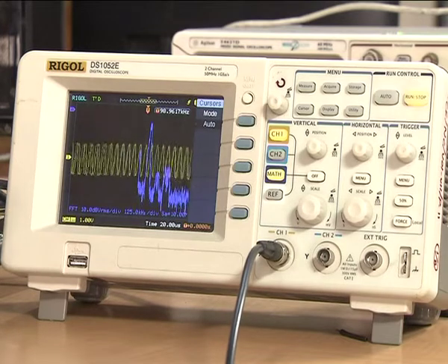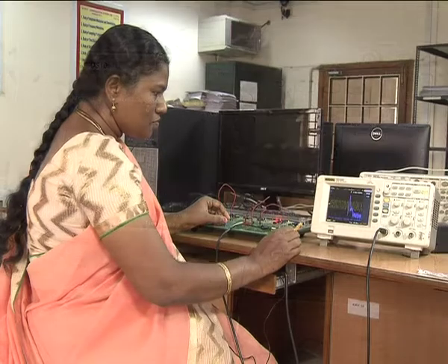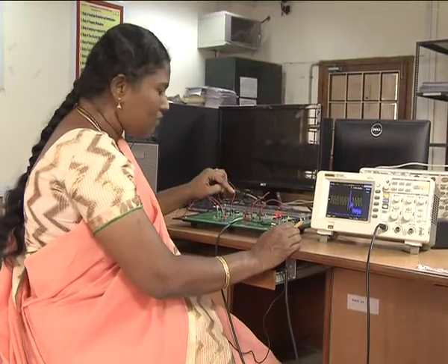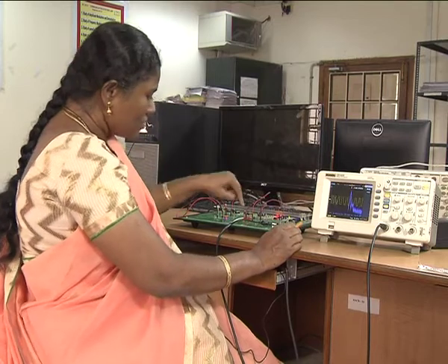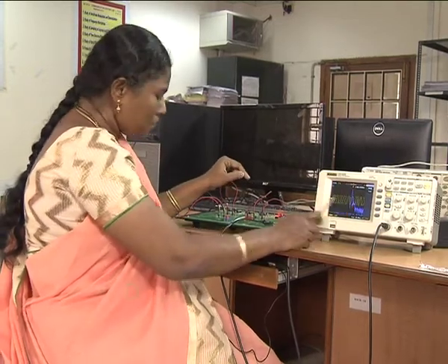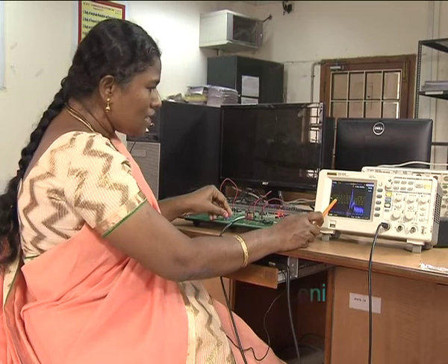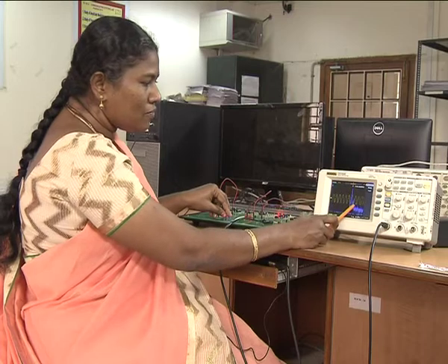To measure the beta and the bandwidth required to transmit the FM signals, we have just given the input to the VCO, and we have noted down the free running frequency of the VCO. As the input is provided, we have noted down the frequency modulated output waveform in the time domain. We can also change the amplitude of the input signal and once again note down the FM modulated waveform.